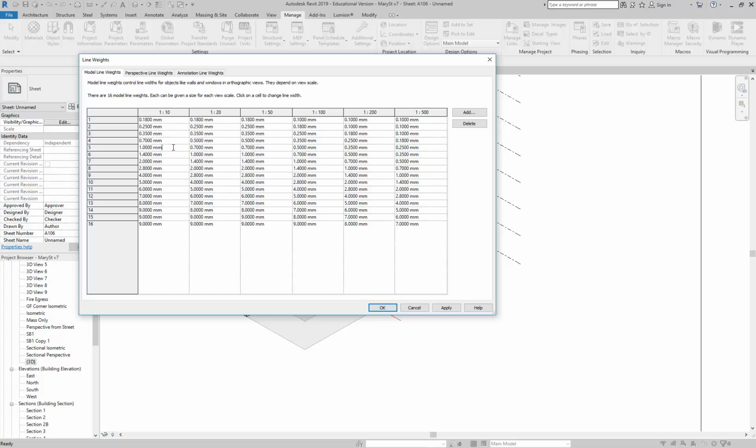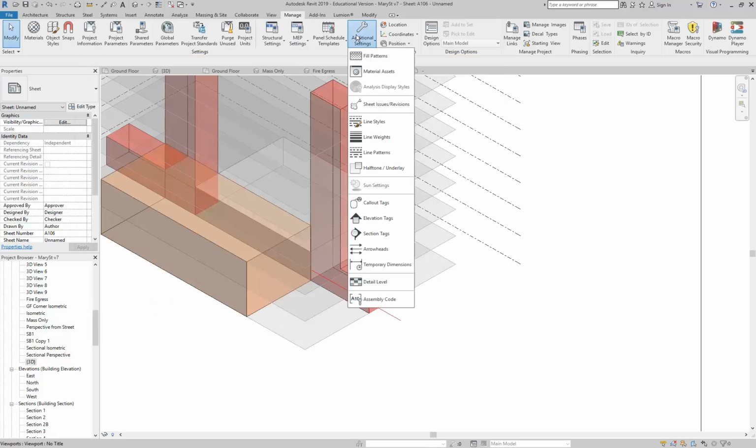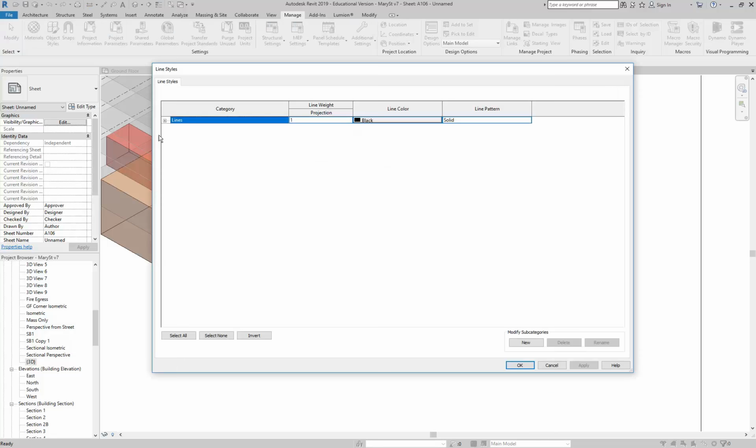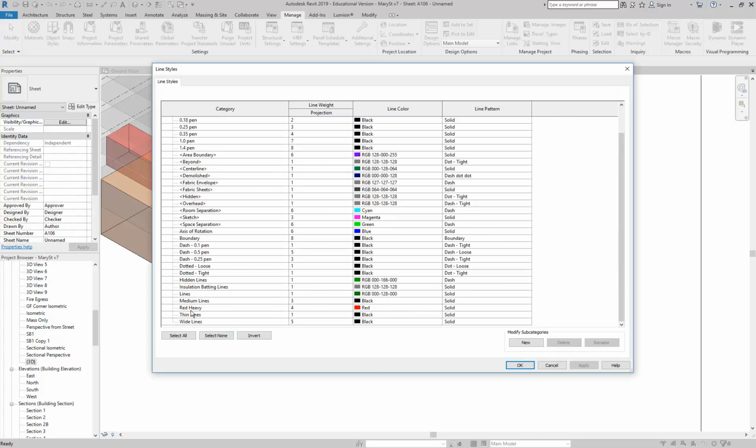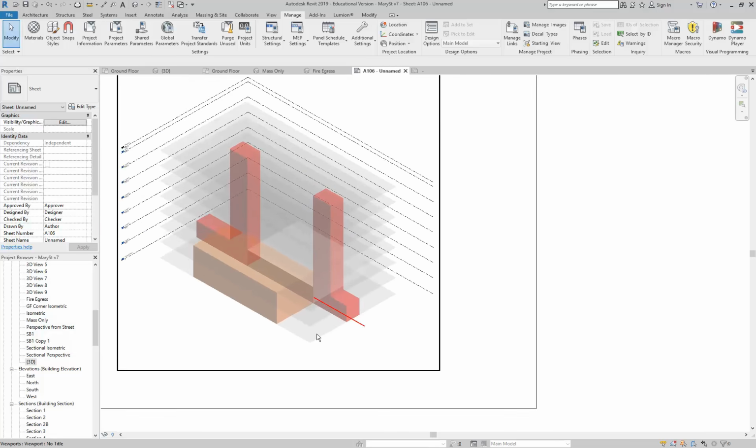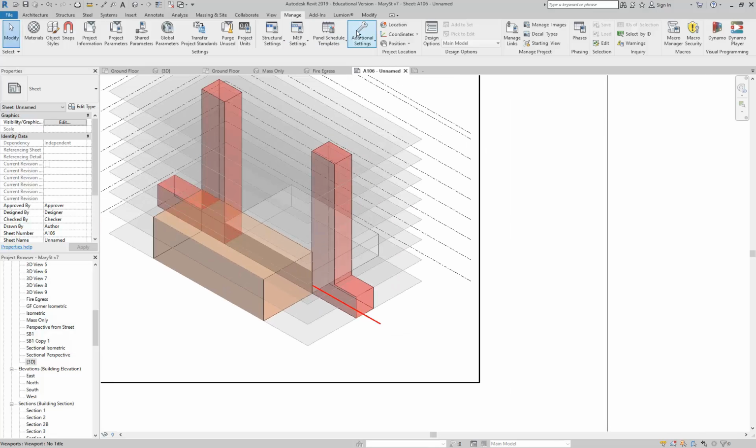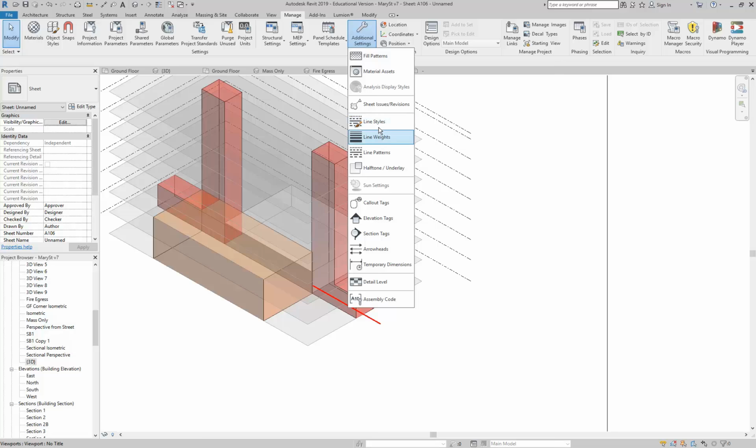So again, when you are working with detail lines, you set a pen, and I've been choosing pen 4, which again is fairly heavy, but not heavy enough, so we'll go back to the line styles and make the red one heavier. Normally I wouldn't use anything higher than about 6 or 7, but we'll go to 7. That's going to be really heavy, but that's what I want. And then I'll make some more, and you can get a really graphical sort of look.